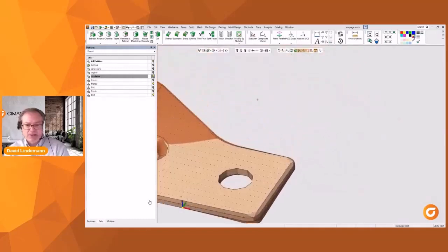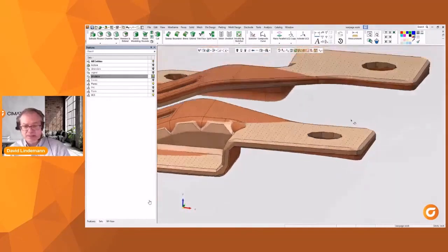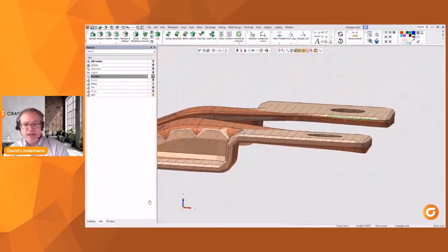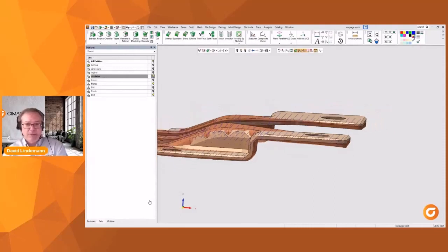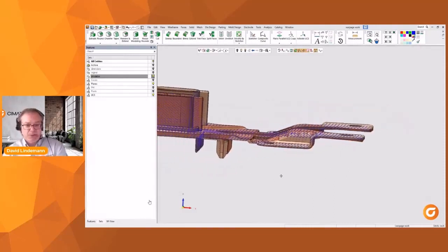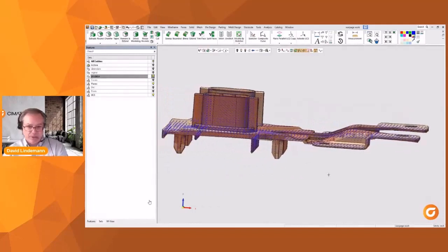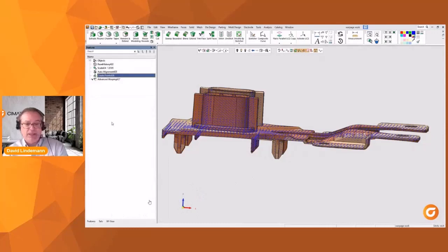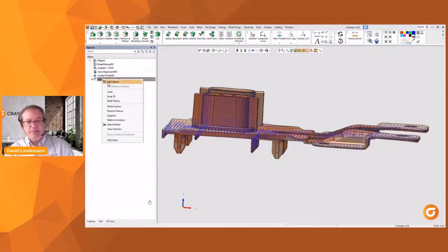So let's zoom up on the end and look at this. There you've got the original STL. All right, so you've got the one that has the warpage, and now the darker orange, that's our compensated model. So you can see just how much it's pushed it in the opposite direction. That's what we would tool our mold to. Okay. Other things will go into that.